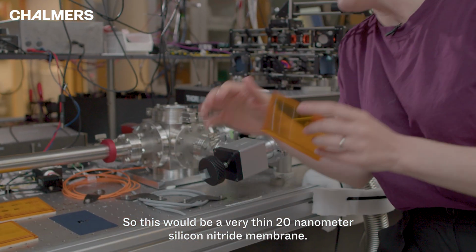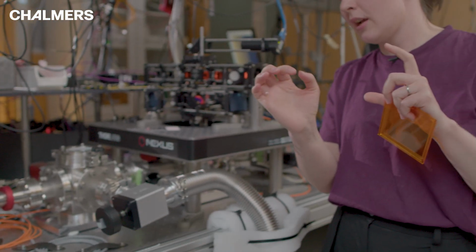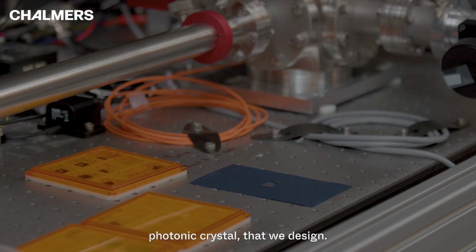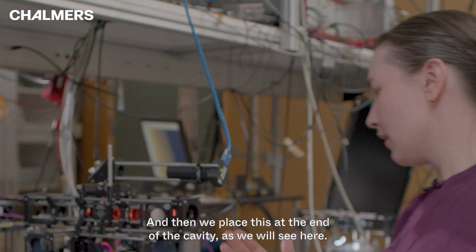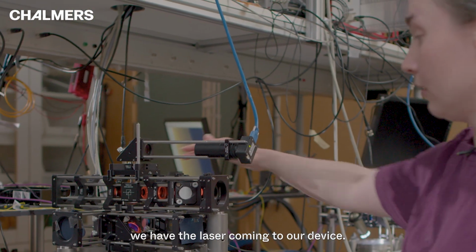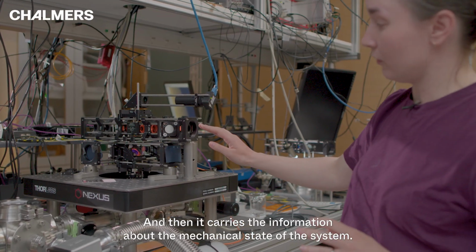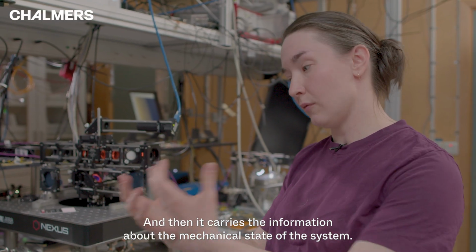So this would be very thin 20 nanometer silicon nitride membrane. And on that we pattern photonic crystal as we design. And then we place this at the end of the cavity, as we will see here. And as I just described, we have the laser coming to our device, reflect back, and then it carries the information about the mechanical state of the system.